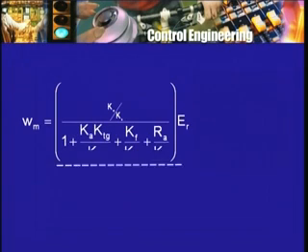And one should be able to use it properly. So in our case then, what will be the numerator? Numerator is only the forward path gain, and what remains of delta is only 1. And so that expression which multiplies ER is ready. I write it again. So omega m is equal to something into ER, and in that expression the numerator will be simply the forward path gain Ka divided by Kb, and in the denominator I will have that expression for delta, 1 plus Ka, K tacho generator divided by Kb, plus Kf by Kt into Ra by Kb.